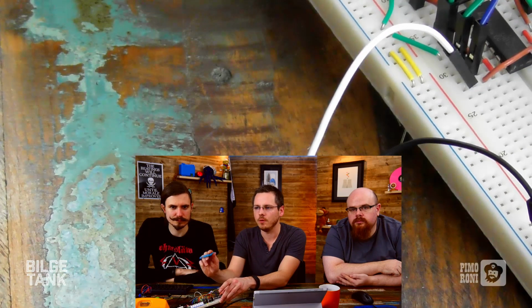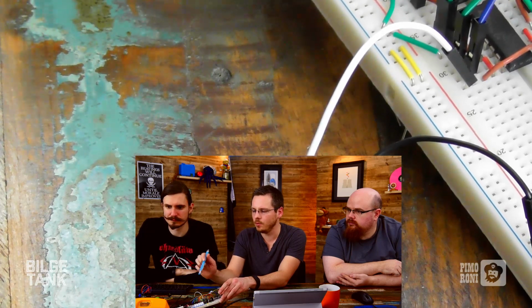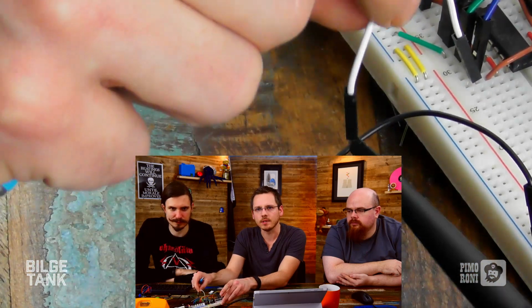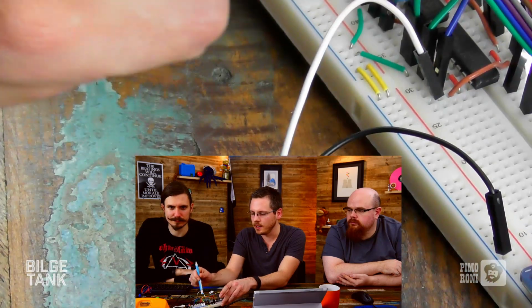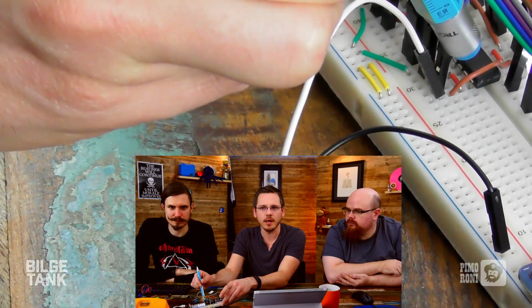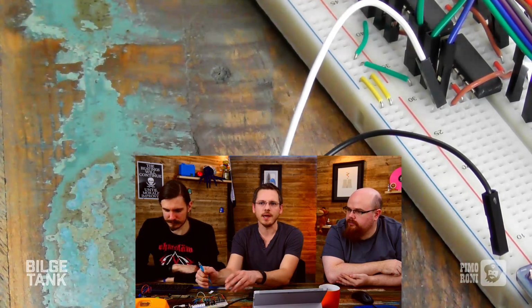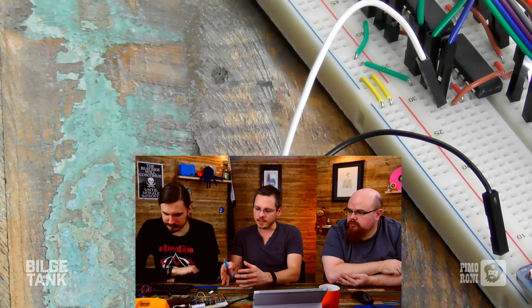which is generating a 1 Hertz sine wave with 3.3 volt peak to peak, because we're actually running on 3v3 here. Our measurement signal, the signal we're actually trying to measure, is just linked directly between the other inputs on the comparators. There's no other discrete circuitry there, they are literally all just tied together, because we want to compare that analog signal against all of our 8 references simultaneously.